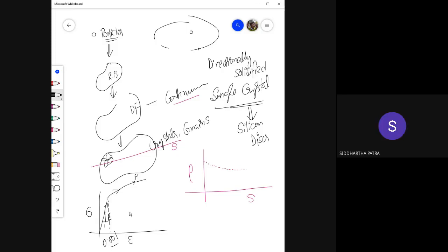But how much permanent deformation? By simply looking at the stress value. It will come down parallel to that line. So yes, you are correct. So the unloading is always elastic. Okay, and that creates the problem.